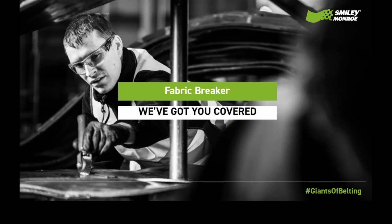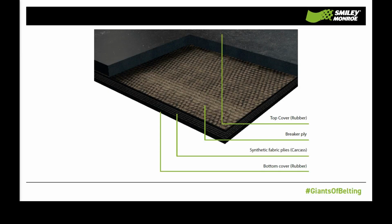So further to the multi-ply standard belts Ryan has just discussed, Smiley Monroe also stock various high specification conveyor belts, namely fabric breaker, Ripstop, and ToughFlex belting. Our fabric breaker belting is constructed with EP fabric plies and an additional fabric breaker ply with a heavy duty top cover to provide more shock absorption to protect the carcass.